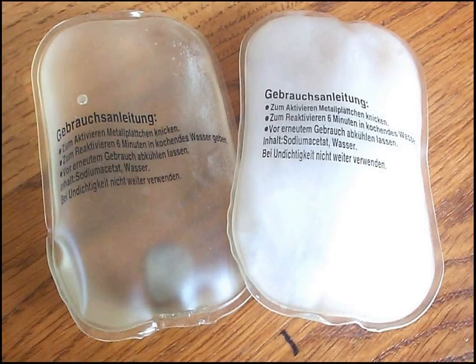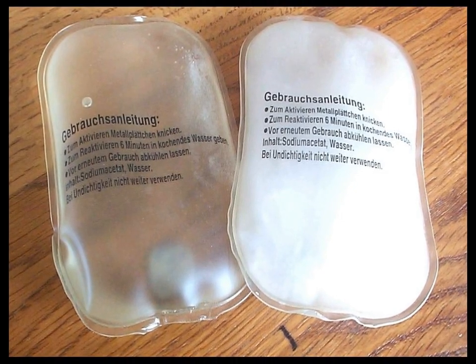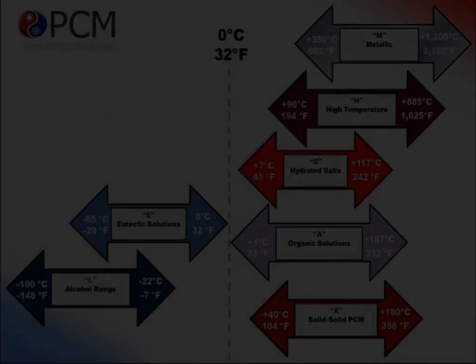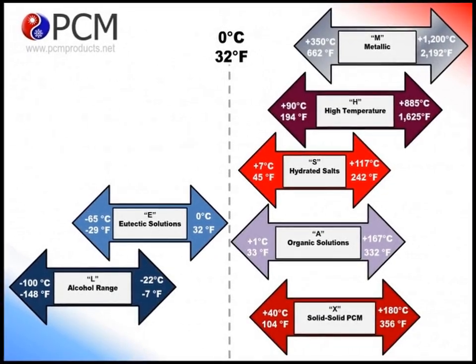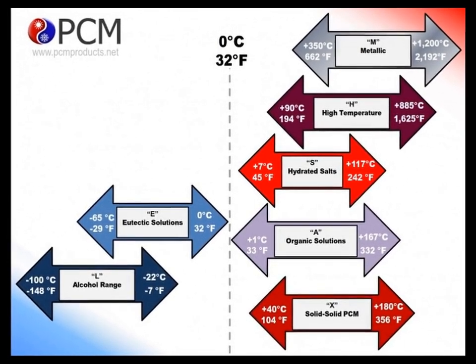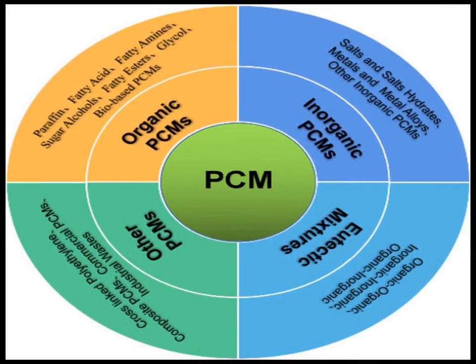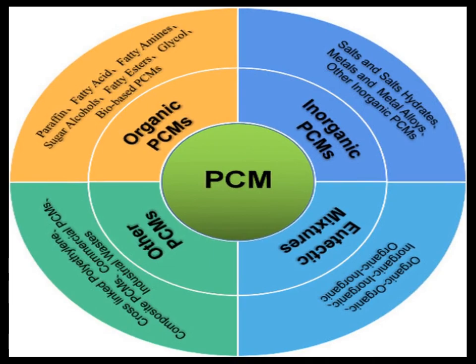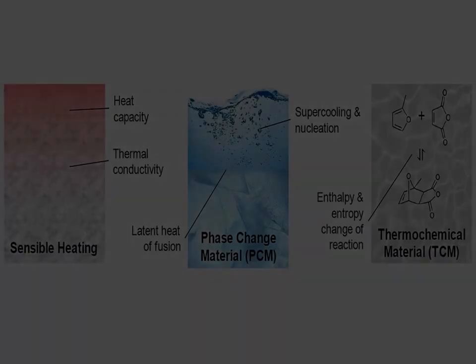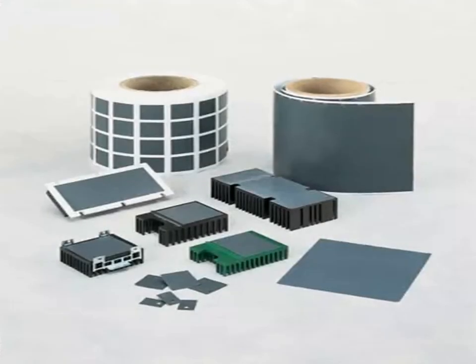Phase change materials, PCMs, are a class of substances that absorb or release significant amounts of latent heat during phase transitions, most commonly between solid and liquid phases, at specific temperatures. This unique thermal behavior allows PCMs to store and release large quantities of thermal energy, making them invaluable in applications requiring thermal regulation, energy storage, or controlled heating and cooling. The key feature that defines phase change materials is their ability to undergo reversible phase transitions with a substantial enthalpy change, typically without a major change in temperature during the transition.